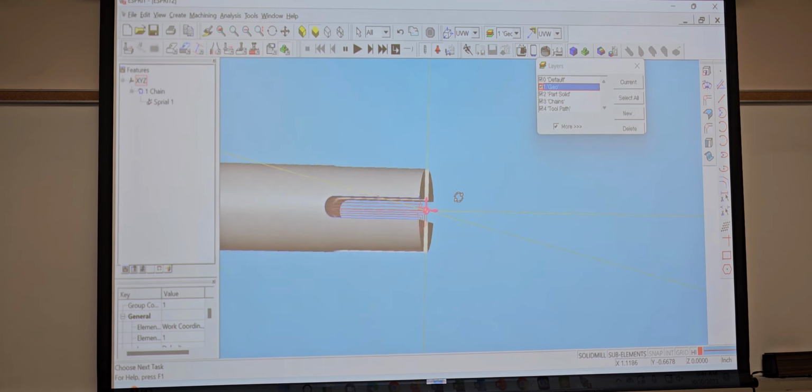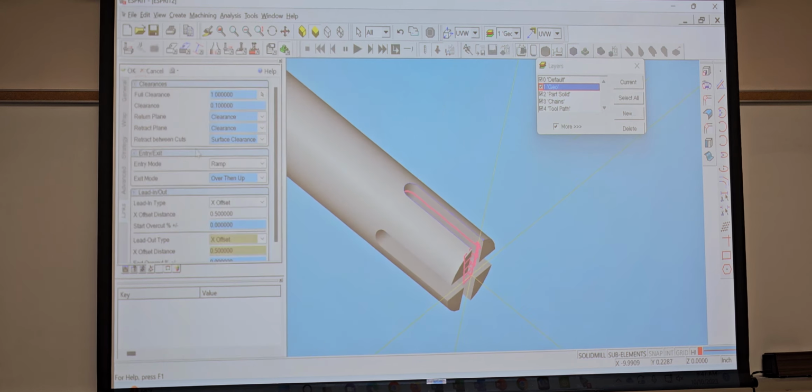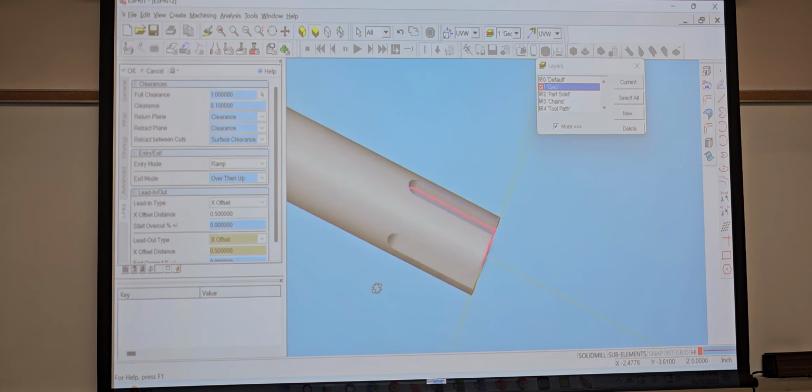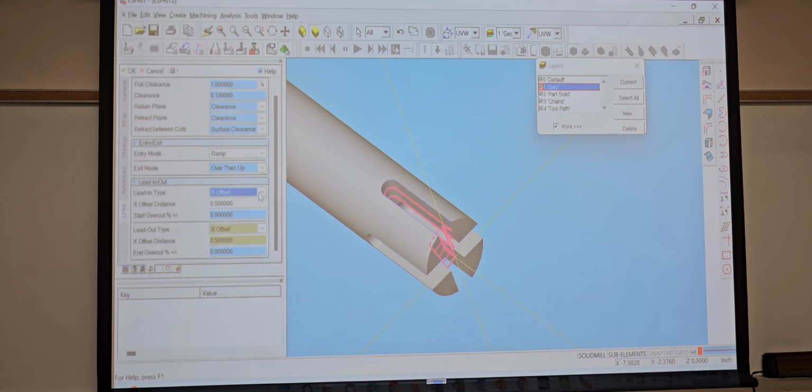Yeah, mine's not working at all. This isn't working out on this one. Alright, so use wrap. I think you gotta do the pockets first, and then use the pockets to put your axis on it. I just did it and it actually was really easy. So you can choose to do it that way, but that's the way I'm doing it. It worked. You're doing the pockets first? Yeah, do the pockets, and that way you have a flat surface to put your axis on. No, yeah, but you really shouldn't have to change the axes. No, it seemed to work better the way I did it last time.